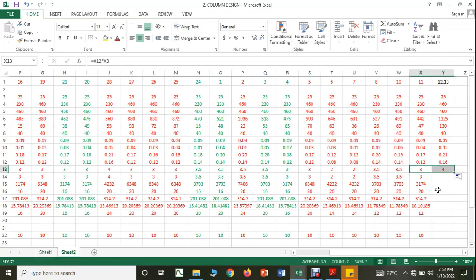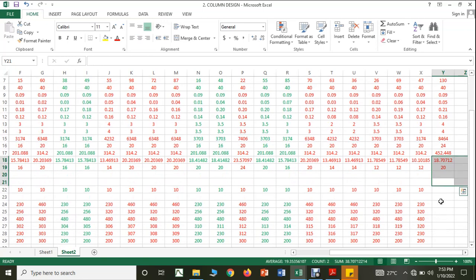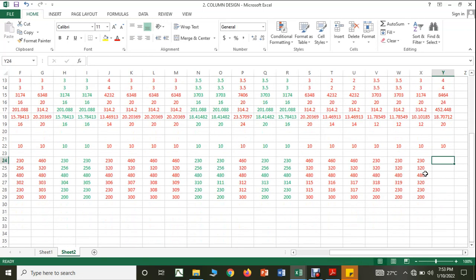And this will be the percentage of steel. 4% I am able to manage in the site, so I'm going to maintain 4% only. And the corresponding percentage of steel is very high, right? If I maintain 20 mm dia, then definitely it will create a very huge value. 0.314, you can see it will create 26 bars. So therefore let us give the 24 mm dia rods. So then it becomes 20. Okay, I can manage with this. And when I'm providing the reinforcement for the stirrups, 10 mm, I am supposed to make 300 mm center to center, right?